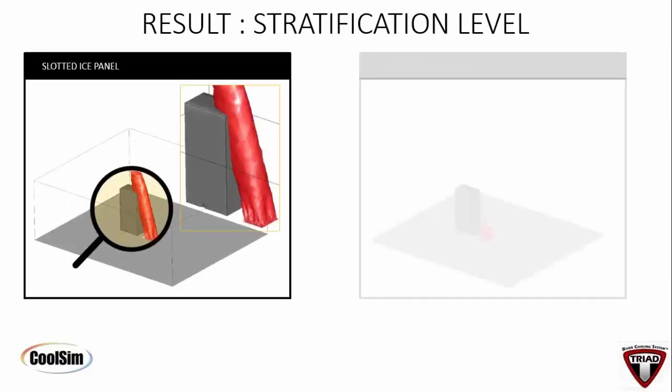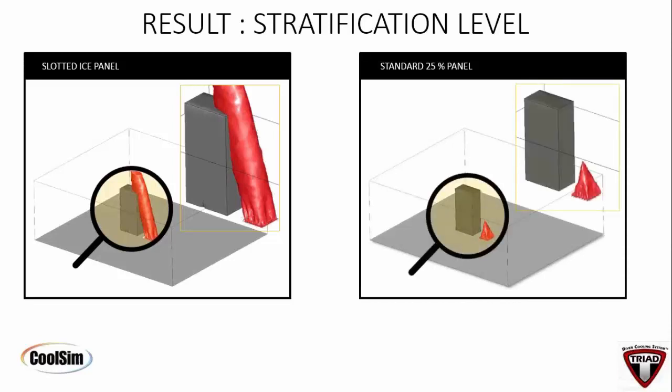And here's again a 3D ISO representation of all flows greater than 180 feet per minute, same as I showed before. You can see it's overlapping the rack right there and causing good cooling, good penetration. This will cause turbulence on the front end of that rack, and it will cause cooling to occur because you're directly infiltrating that rack with cool air. Over here, not so much. I mean, you've got to hope that this air right here is cold enough to cause the heat to transfer through the air by itself without the help of any convective force, and that's tough to get done.